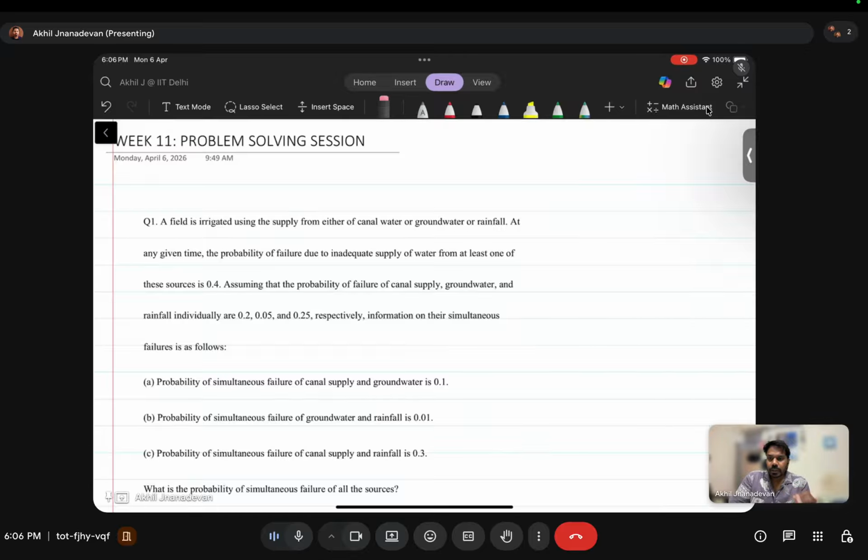And also there will be assumptions in the model, as the model may be assuming the flow as a uniform flow, or the model may be assuming that it is lumped. When we deal with a lumped model, the spatial heterogeneity is ignored. So these assumptions will be there, and that will create a model uncertainty. So every hydrological model or every hydrological variable will be related with something called uncertainty. So there is a need to quantify this uncertainty.